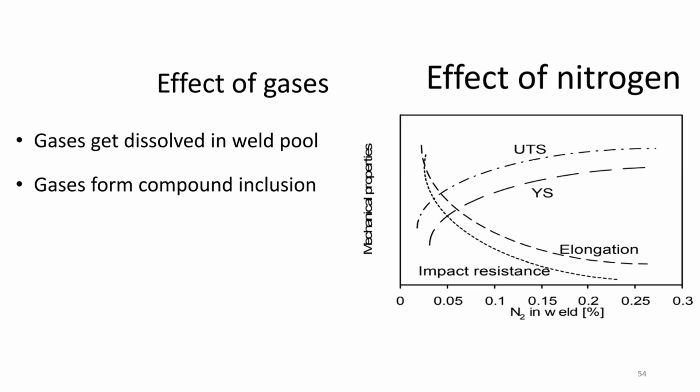These inclusions cause problems when some tensile force is applied: there is more likely formation of cracks from the inclusion and matrix interface, which will act as a delamination type of effect. So the cracks will initiate from that particular part, and these render your material low in strength.